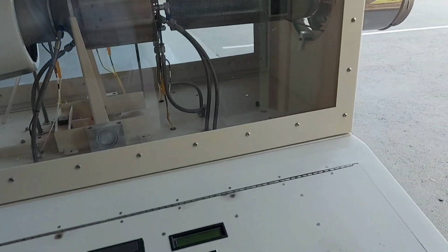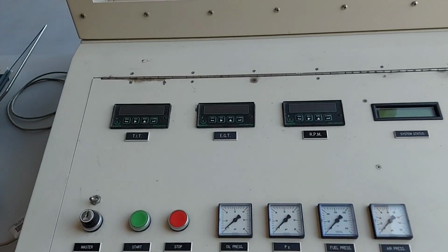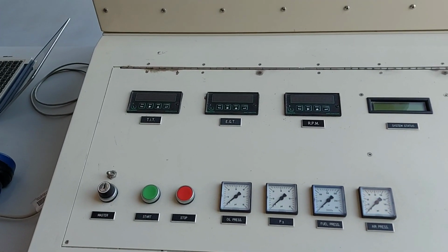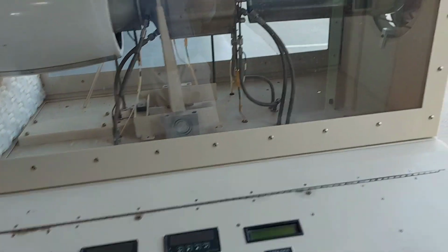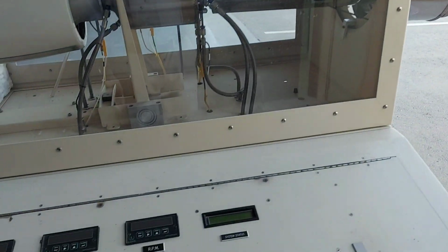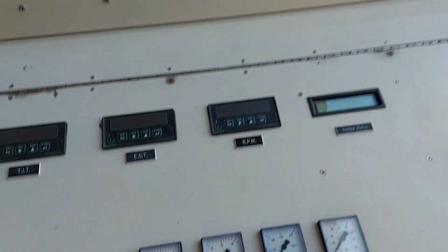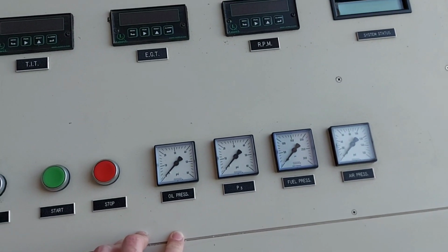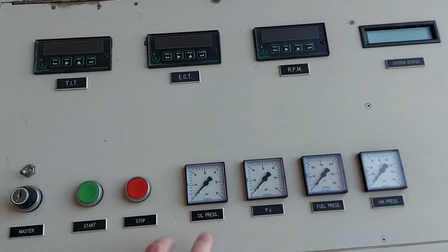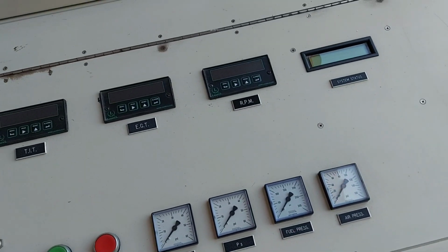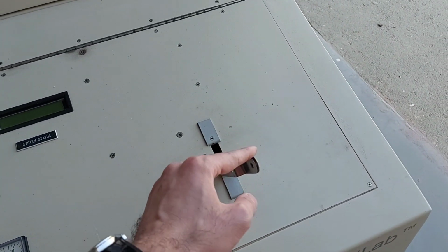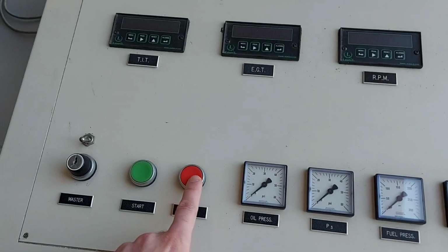In this case, the turbine engine has stopped functioning because of low fuel. We put 10 liters of diesel inside the engine. If this happens, you need to turn everything off, wait for it to cool down, and fill it up with fuel again for the next run. If the fuel was sufficient and you finish the run, make sure to put the throttle back at minimum power and press stop.